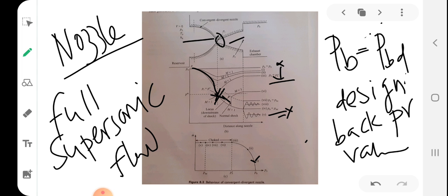You can see that the third and fourth values are associated with choked flow only. Choked flow means that at the minimum area, Mach number has become 1. Whenever the Mach number becomes 1 at the throat, the flow is choked and the passage is no more a Venturi. It has become a nozzle.